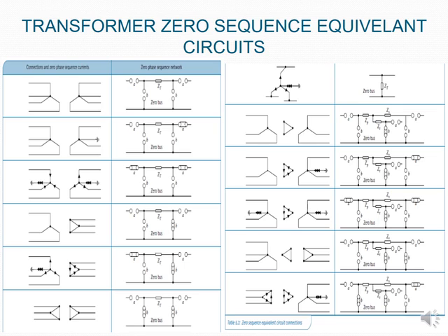Then for your star to delta connection, you must just also note how your connection will look on your zero phase sequence. And then on your star delta, your star being earthed, again, how it will look. And then you've got your delta delta scenario, and you can see it just goes right to ground and there's no connection on either side of your buses in there.